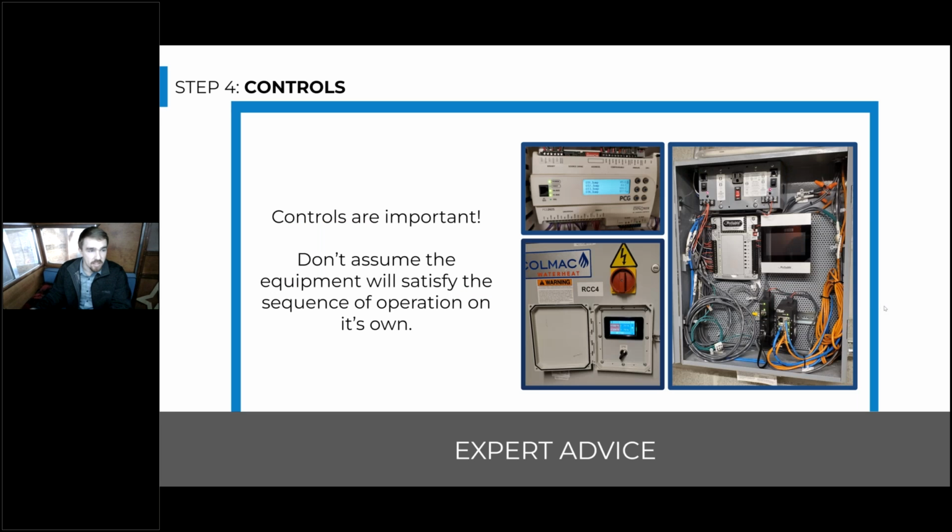So the first mention in that is controls, and that they are super important. I did a lot of startups at Colmac, and there were quite a few projects where there wasn't even a temperature sensor in the tank, and no one had actually considered controls. So the heat pump was just sitting there, powered off, nice and happy, because it had no clue what was going on in the storage tank.